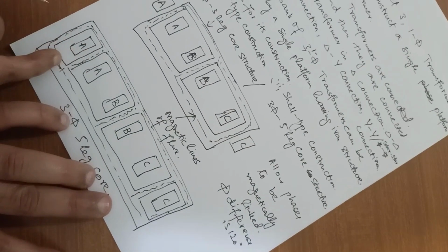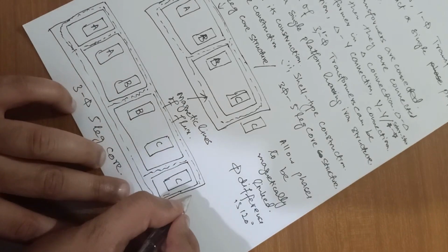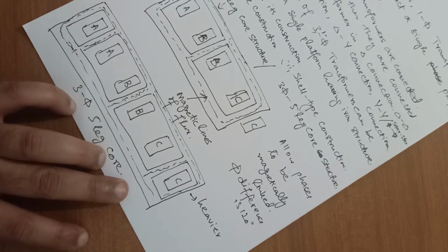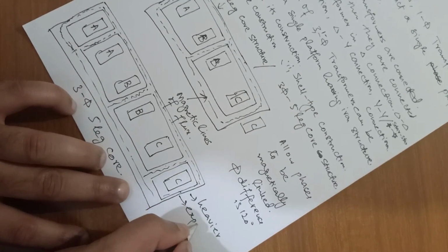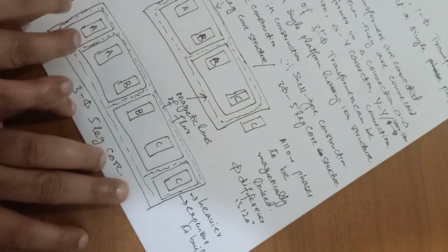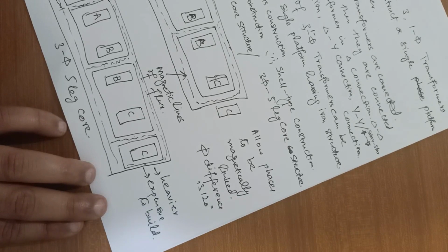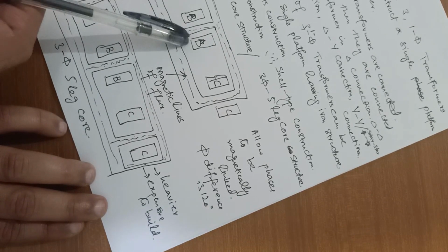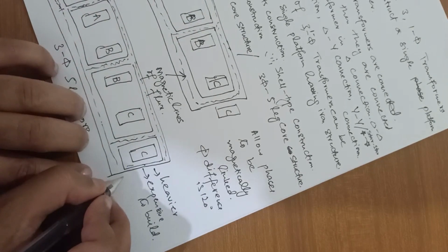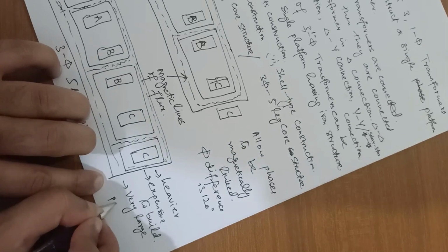However, if we construct this three-phase 5-limb type, then it will be relatively heavier, right? This structure will be relatively heavier, and it also will be expensive to build. This shell type structure of 5 limbs will be relatively expensive to build. So that's why we often prefer this structure, right? The 5-limb cores are generally used for very large power transformers.